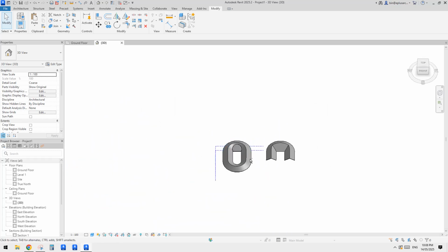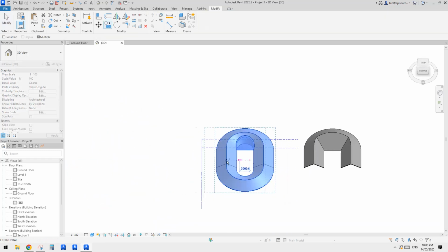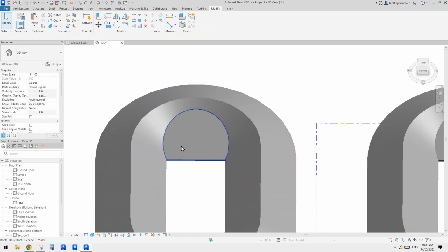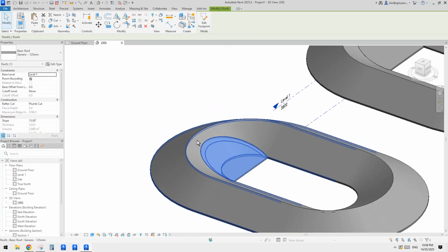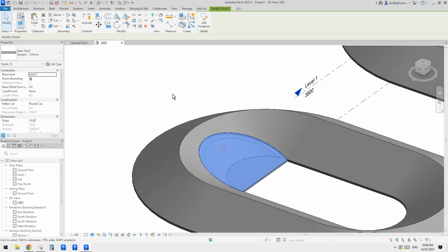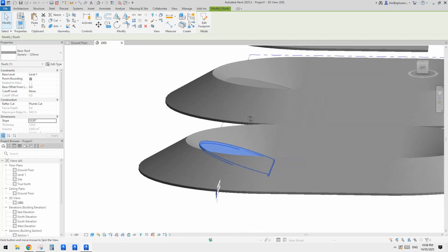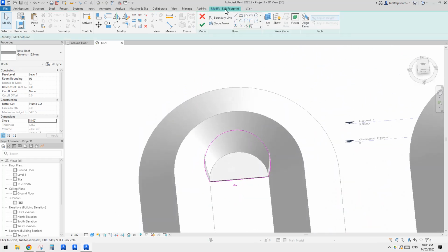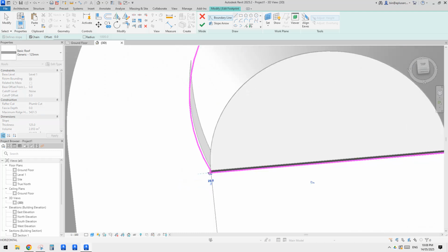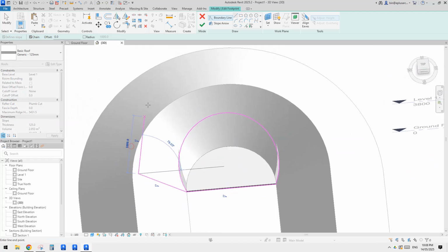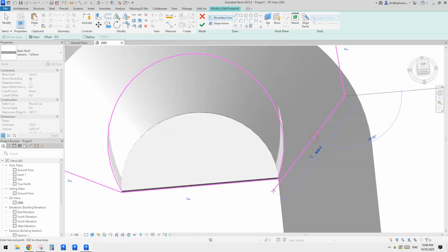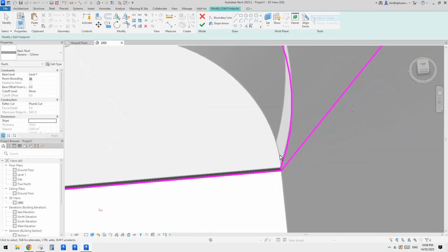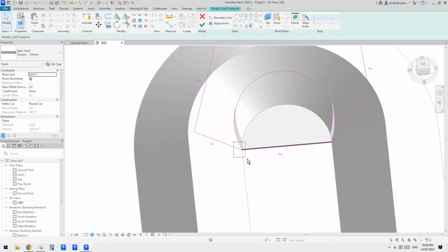Okay, so I'll just copy this one to here. What if we want to change the pitch? That's quite simple. For example, if I change this one to 18 degrees, then we might need to increase the size a little bit, because we want to make this roof intersect with the other one, so we can have the edge, right?